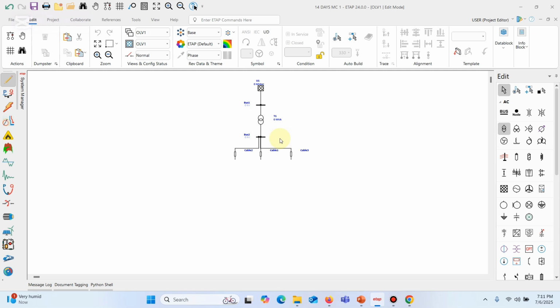So to mitigate this, we can actually delete our connection points. Just click on the connection line and tap delete on your keyboard. So it actually goes off. Click on the connection line, tap delete, and that goes out. That's one. Now, to make it look a bit more presentable, we come to this bus bar and we click on it.